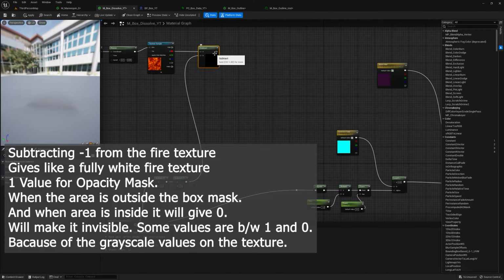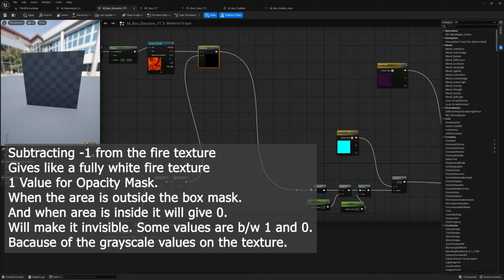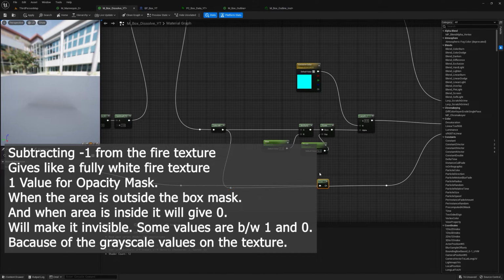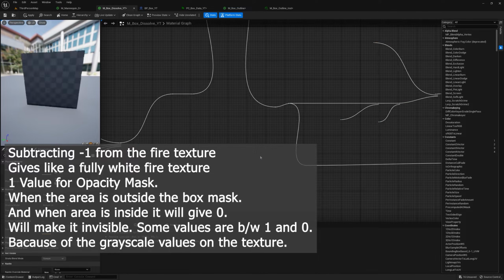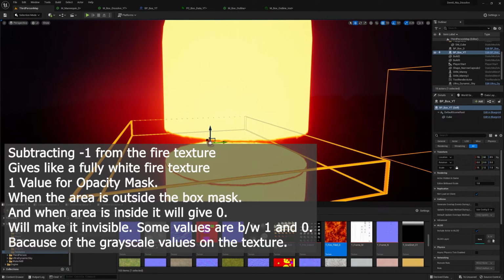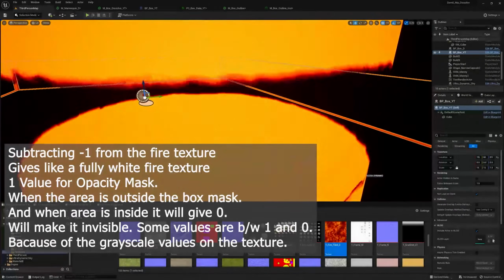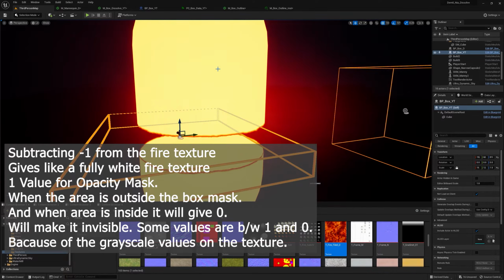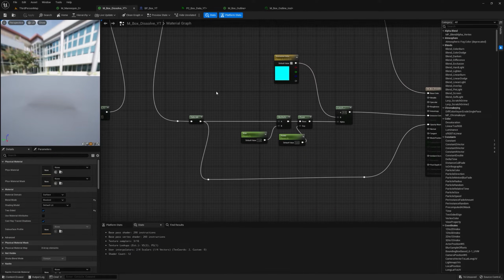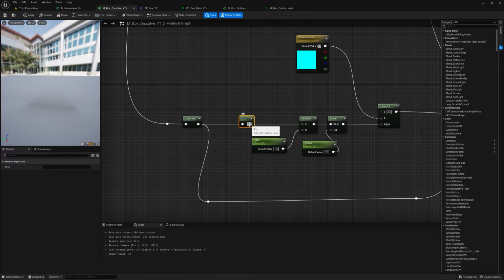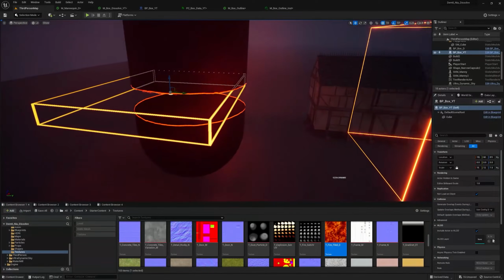And now we can connect this value to the saturate here, and now connect this without the 1 minus, like this, and delete the 1 minus here and click apply. So here we get something strange like this. Here you can see that the edges have this flame effect, but also the MC color is bleeding into the rest of the mesh. So in order to fix this, we can just add 1 minus here, so it will only happen at the fringes. So now click apply.